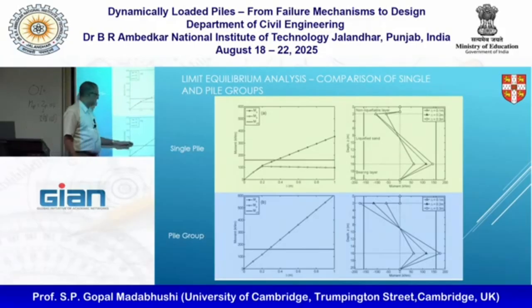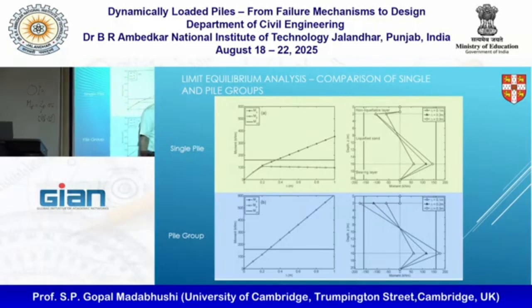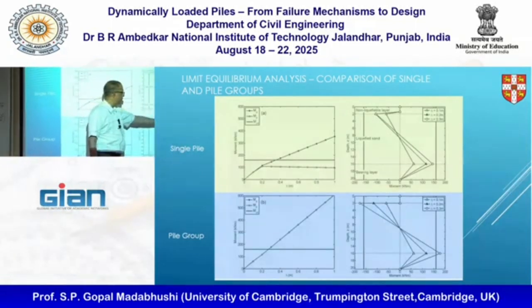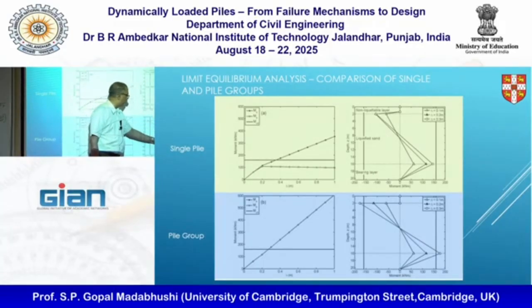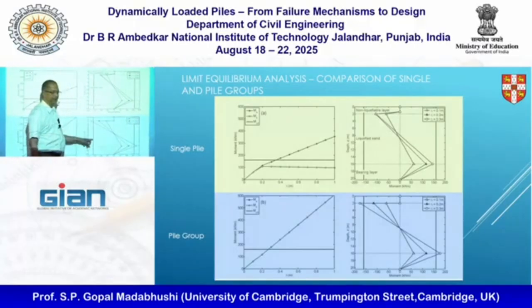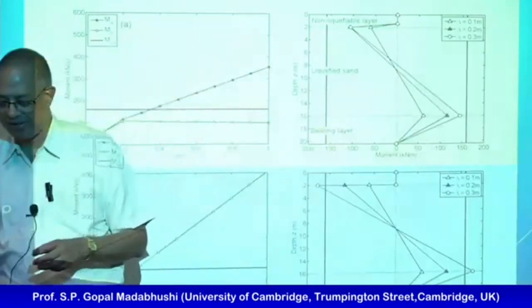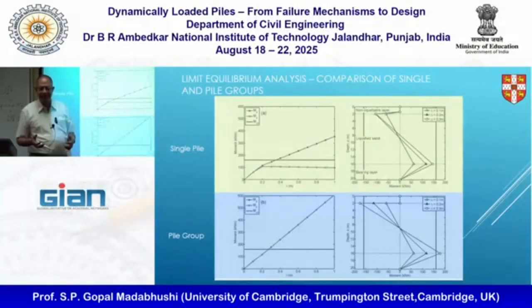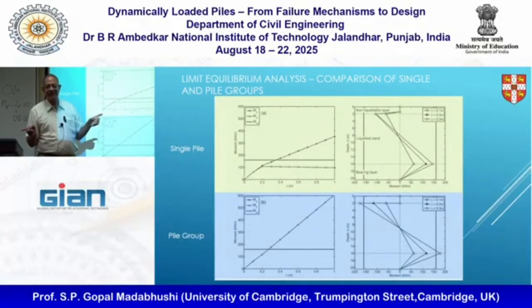Yeah? So we'll do the same thing, different levels of deflection of the pile cap, 0.1, 0.2, 0.3, and you can see for 0.1, it's okay, 0.2, maybe okay, 0.3, it died. Yeah? And it dies because MA and MB are both the same because of the frame action. Both will form hinges. So the pile will die by forming a hinge at the top and a hinge at the bottom, like what I've shown in the very first slide.